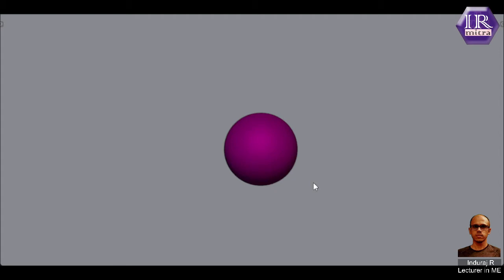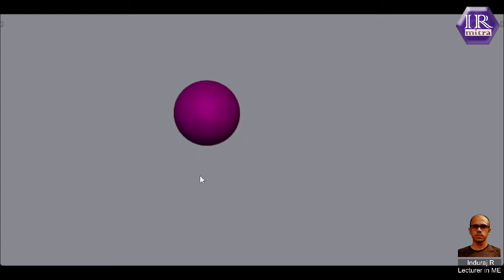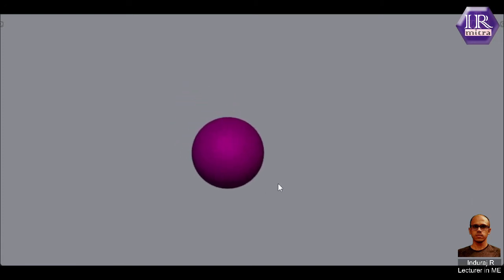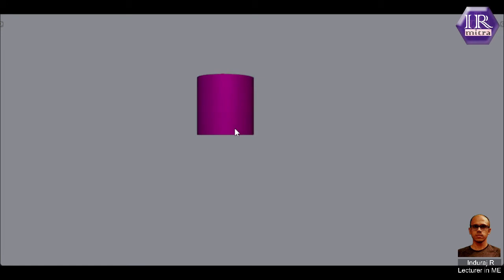What we will be doing is drawing different views of this sphere from different angles onto the 2D drawing sheet. From these multi-view projections, an engineer should be able to identify the shape of the 3D object. So obviously, for a sphere, at any angle, the views are going to be circles. The next 3D object we are having is a cylinder. So we have to create the multi-view projections of this cylinder. That is how it is going to look like on a paper from different angles.